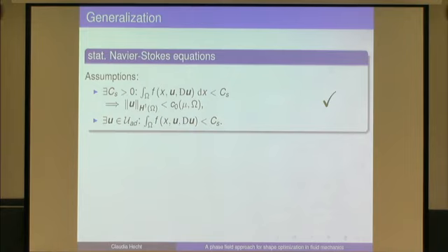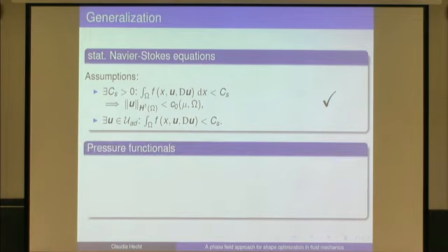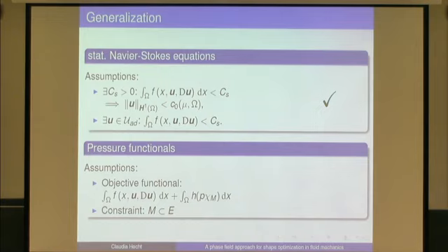And of course it's also interesting to measure different things for fluids, so for example the pressure. So far I only considered the velocity, but you can also include pressure functionals because that's an important quantity for fluid mechanics. And if you want to minimize a functional depending on the pressure, you have to include an additional constraint. So you have to assume that in every part where you measure the pressure, there is fluid present. And the reason is that before, the velocity vanishes if no fluid is present, and so you know what the velocity is doing outside the fluid region. But you do not know what the pressure is doing outside the fluid region. And so you have to include it. You can only take the pressure into account if you know there is fluid present, because otherwise it's not a relevant quantity. But then you can again show the same results.